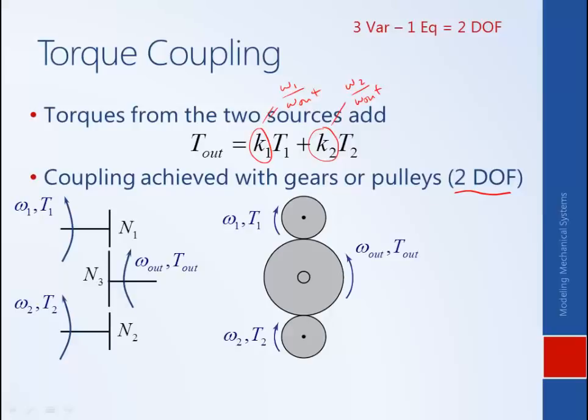In practice, however, there's only 1 degree of freedom that we can play with. And so think about why that is for a second. The reason is because in practice the output is determined by the demand of the driver. When the driver steps on the gas, when he steps on the accelerator pedal, he is in essence requesting a certain amount of torque at the wheels.